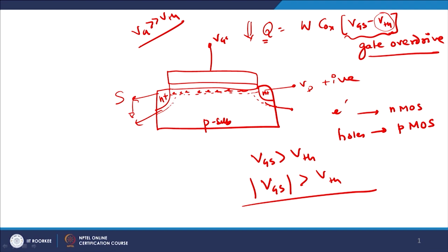So, this is what we get from the basic configuration or idea. But you see that when you do not apply any gate bias, this is perfectly like this, exactly like a straight line, which means that the total number of charge carriers per unit area is almost constant as you move from source to drain. It is perfectly symmetrical in nature.